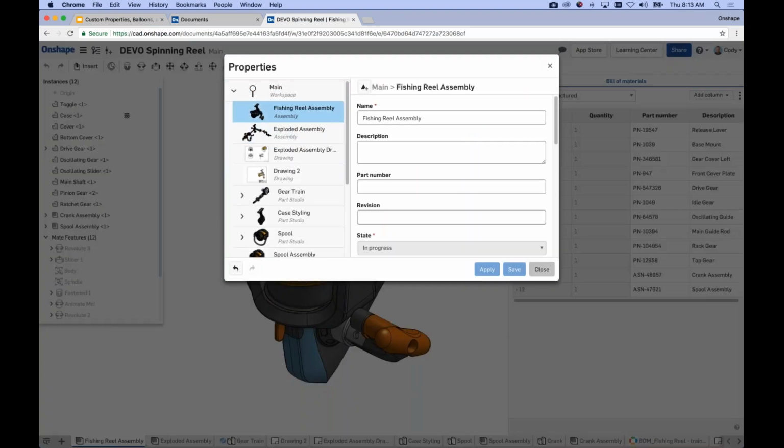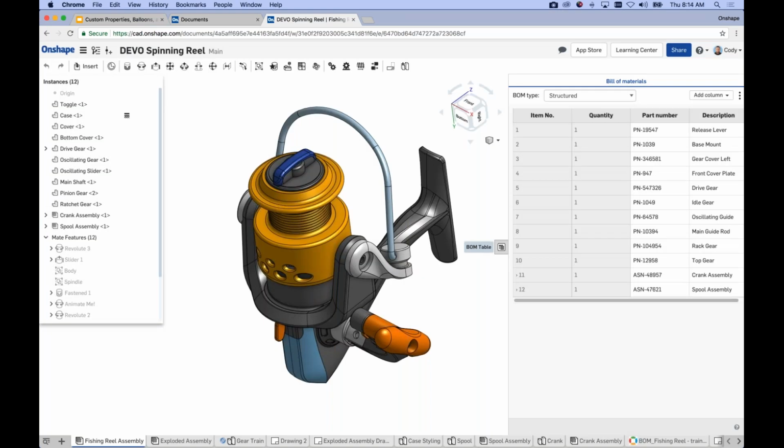So, I'm somewhat removed from the assembly, right? I can edit the metadata here. Here's description and part number and so on. But I'm not looking at the assembly. I'm not in the assembly. So in my opinion, just going into part number, double clicking and typing in a new part number, it's a really powerful thing to be able to do just right from the assembly level.